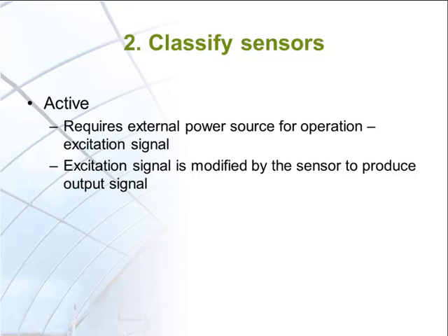Voltage variation of a power supply has direct impact on the sensor performance. Providing high-quality external power source is important for active sensors, especially for sensors without built-in voltage regulator. Two examples of active sensors are provided here.